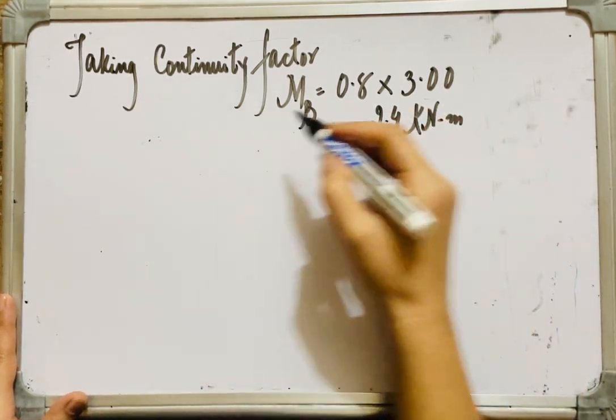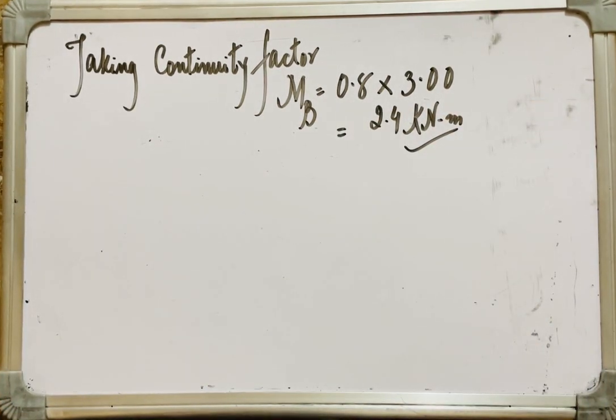All right. Once again, I'm saying that I'm applying only continuity factor to calculate my dead load bending moments, and not the impact factor. That is because of live load, and we take it only in live loads. In dead loads only the continuity factor, in live loads both continuity as well as impact.